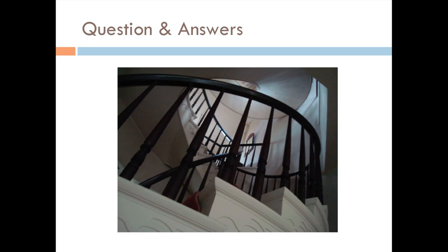So say you're applying stucco to the rainy side of a building, like a stone farmhouse. In that situation, would we be better off to use something that's less porous and more likely to resist the moisture? Well, in that case, I would recommend using something more flexible to accommodate the movement of an old farmhouse, because that wall, if it's built with what would be a rather flexible and vapor permeable mortar to begin with, you don't want to trap that water.